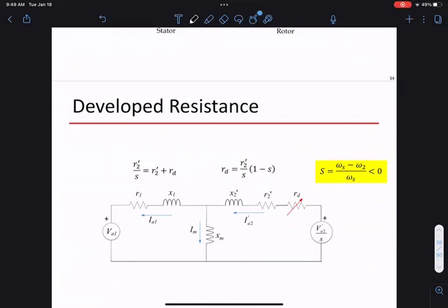Okay, so this is our type 1. Again, this is why it's simple. When you look at these equations, nowhere does the fact this is in a wind turbine come in. Because who's doing the hard work is the gearbox. The gearbox is making sure you have a good slip. Once that is determined, your generator does not care that it is in a wind turbine. It just generates power that way. Okay, and that's why it's simple, and why we're not expecting this thing to perform very well as a generator. But this is the first step.